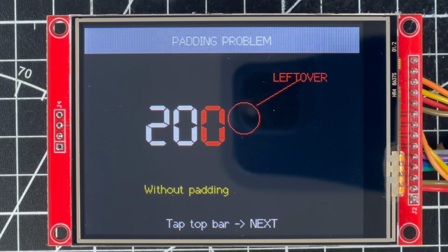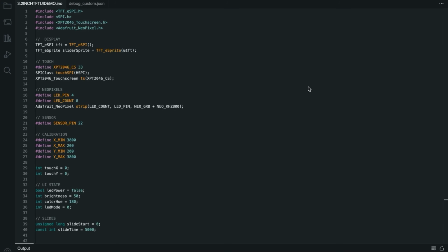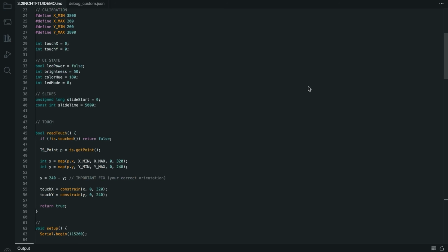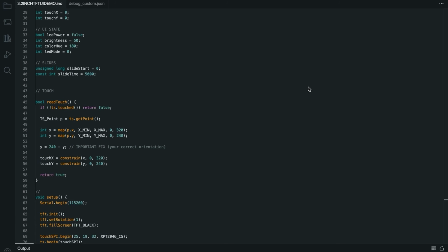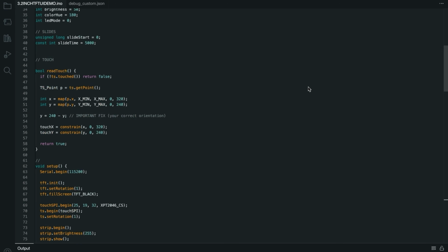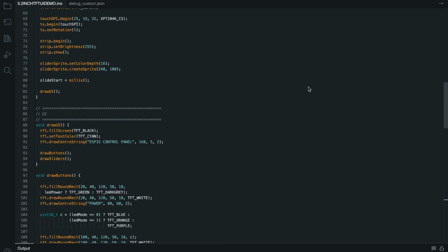When you call a drawing function, the library fills a rectangular area to the specified width with the background color before drawing the text. The height of this padding area is determined automatically based on the font being used. You must use a foreground and background color using set text color for padding to work. It is best to set the padding to the maximum possible width your text might reach. You can use the text width function to calculate this dynamically.